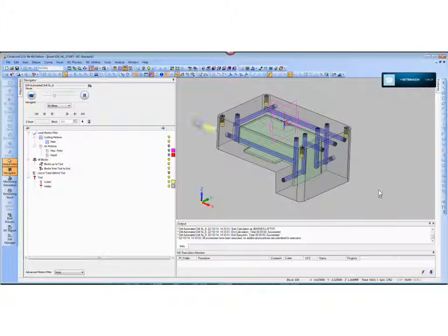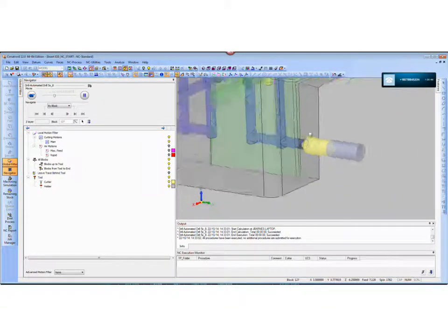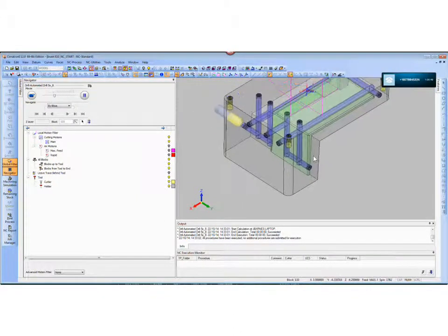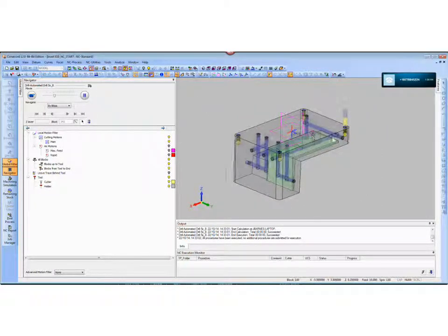Now these water lines I am processing with a starter drill, but it's really for 2 reasons. Number one, I want to have a big chamfer lead in on these holes. I think that's an advantage. And secondly, you're going to see some logic being used here in a minute. This is the tap drill coming in and tapping these holes. But in a second, you're going to see that not all these holes are drilled in the same way. Even though I use the same sequence, the sequence can have logic built into it. And I'll explain that in just a second.